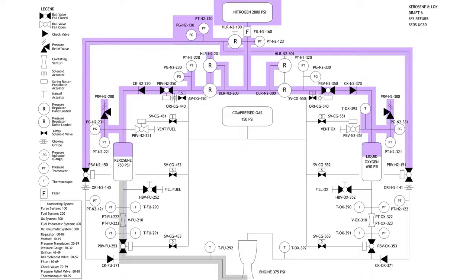That's transient, that's unsteady state, and that's different mass flow rates to your engine, and that affects the efficiency of your engine and also can cause combustion instabilities. And so it's dangerous. So what we don't want to worry about is having bad data. So we're going to get good data if we have steady state functioning. So that whole pressure-fed system is going to be our steady state. Are there any questions about the purge, the fuel, or the oxidizer, pressurization, or propellant system? The solenoid valves? Yeah, I'm going to explain the solenoids in a second.